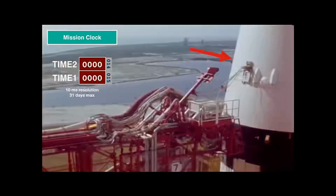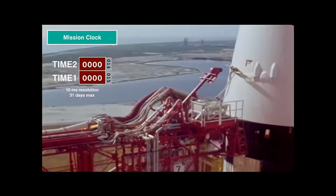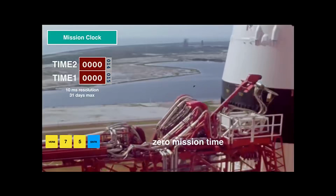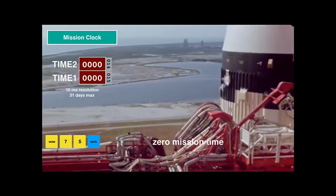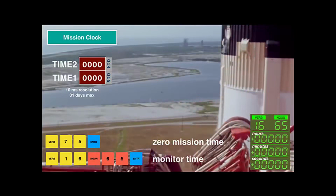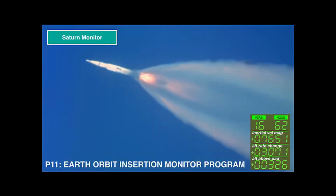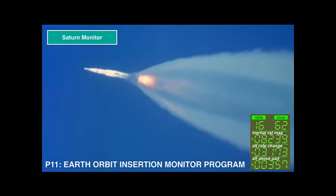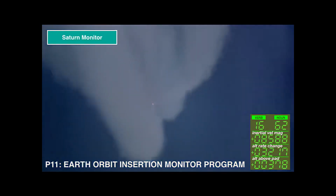With the cutting of the umbilical cables, which you see right about now, it has started the mission clock. In case this trigger fails, one DSKY key is always prepared with verb 75 and just waiting for enter to manually start the mission timer. We can display the mission elapsed time at any time with verb 16, noun 65. During the flight with the Saturn V, the Apollo guidance computer is only performing passive monitoring of the flight. Control of the Saturn V is with its own launch vehicle digital computer and the instrument unit ring.